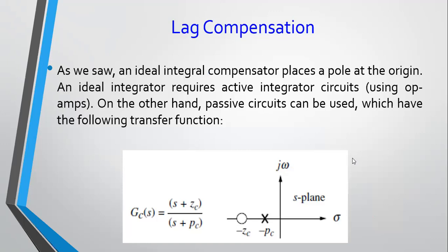Now, the next topic we're going to cover in the next video is lag compensation, where we are not using a pure integrator, but we're using an integrator which is not at the origin, which is very close to origin, and the main reason for that is that you get passive circuits. So we're going to have a video to cover the lag compensator.